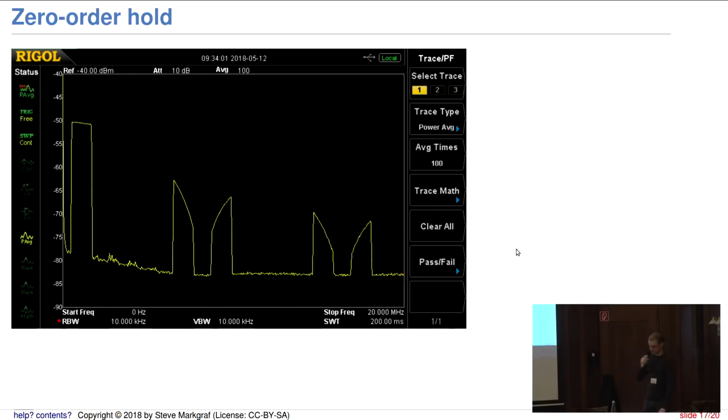And this guy who built this AM marker generator also did some further experimentation with the fl2k dongle, and measured with the spectrum analyzer. And he noticed that you have this zero order hold effect, because the samples output by the DAC is basically a staircase. There's no reconstruction filter, so this is called a zero order hold, because the last sample level is being held until the next sample. And yeah, this gives you this filter effect.